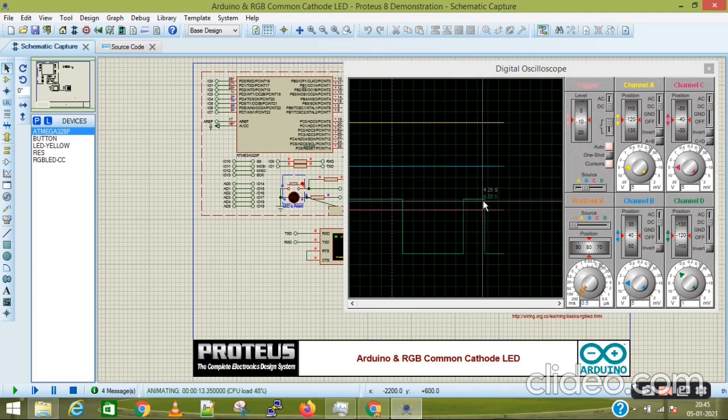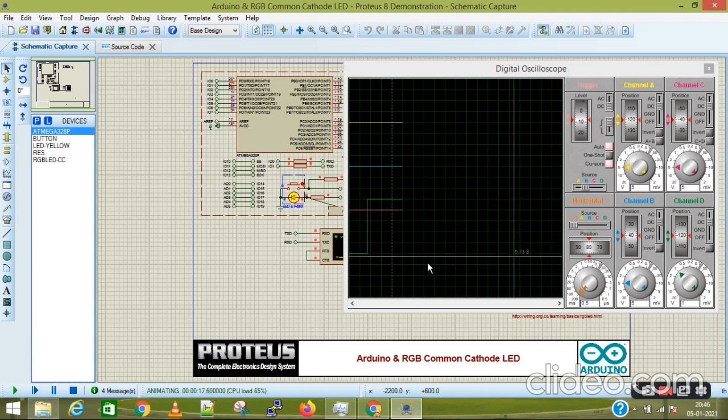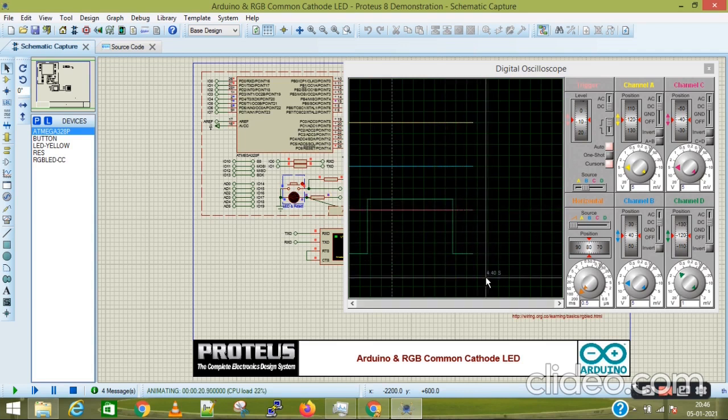It will remain high for half a second and remain off for 1 second, and again remain high for 0.25 of a second for the second part of the wave, and low for half a second, and for the last part it will be stretched off for a bit. For 2 seconds it will stay high and then remain low for the rest of the 4 seconds, as according to the instructions. And this will keep on repeating, since this part of the code was in the loop function, and we know that the code within the loop function of the sketch keeps on running over and over again.